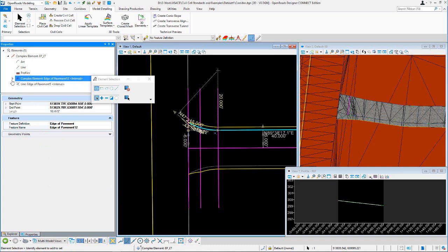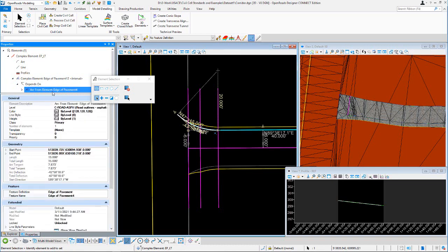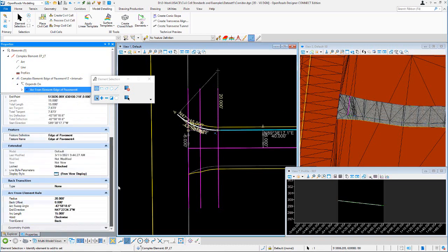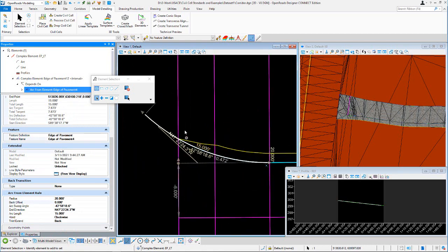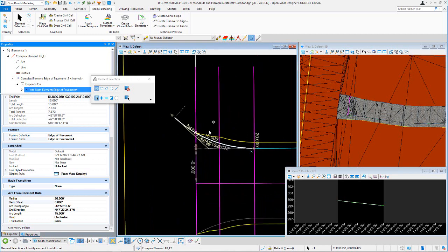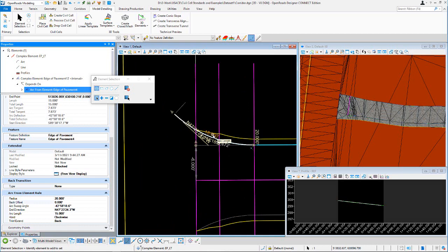Alright, that's not the one I'm after. So, it's actually the arc, which is trim. So the arc from element command here. Then you can obviously change your radius value here, and that length, which is basically what we did. We copy parallel to create this, and then from that intersection we're placing an arc, 20 foot radius that is 15 feet long.